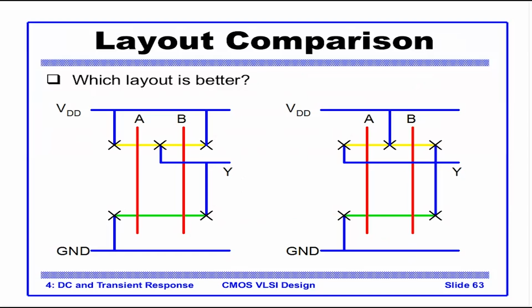This chapter was, I agree, a bit more complex than the earlier chapter, but it sets the tone for the coming chapter. The first chapter concentrated on how we design, how we stitch and put together different PMOS and NMOS to make a complex gate. This chapter concentrated on how we decide how wide the transistor should be, and once we've decided how wide the transistor should be, how we calculate the resistance and capacitance, how we annotate those values, and how we calculate the Elmore delay.